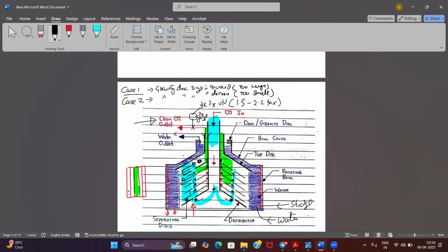So I have to give certain time in my purifier so that my oil can stay in my purifier for some time, so that purification can happen. The centrifugal force will act upon these solid particles and my water molecules to separate them out. So I have to give some back pressure to my oil, otherwise it is just acting like a pump, isn't it? All right.